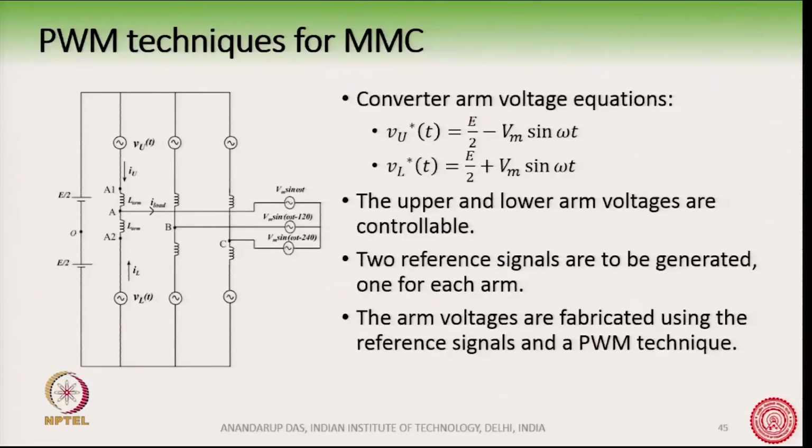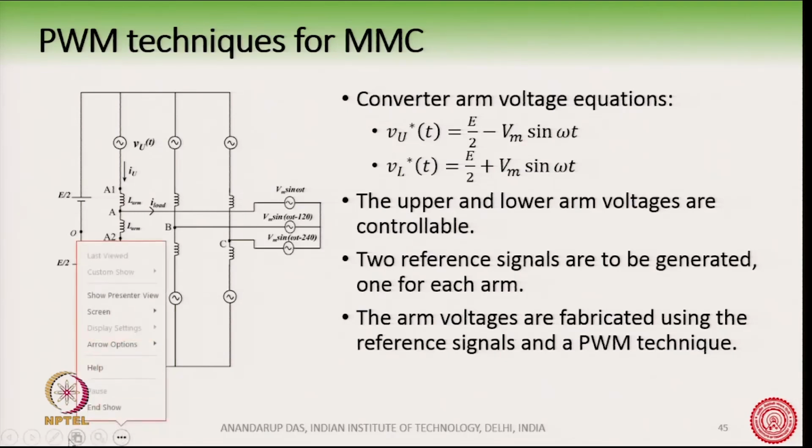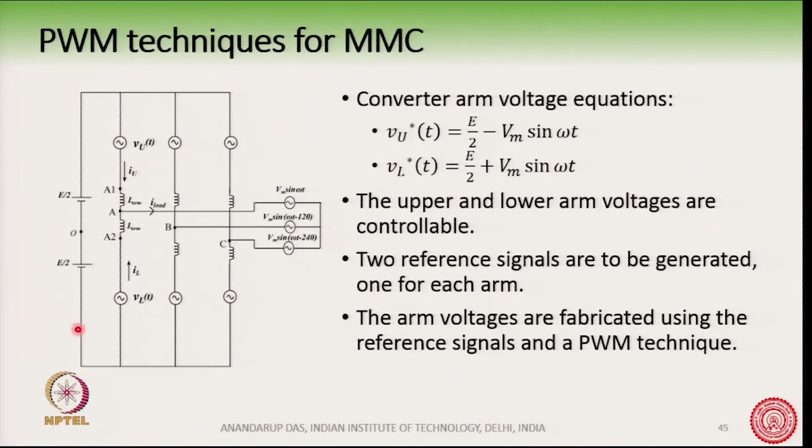Now, from the basic operation of MMC, we have understood that the arm voltages are controllable voltage sources, and these controllable voltage sources are represented by these equations.